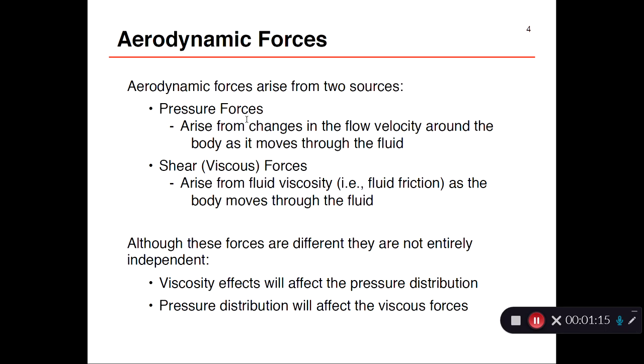So what are the forces that we are interested in? We are interested in the aerodynamic forces on the body, whether it's an airplane or an aerofoil. We are going to be worried about the pressure forces, which are caused by the change in the flow velocity. For example, we have seen Bernoulli equation in incompressible flow.